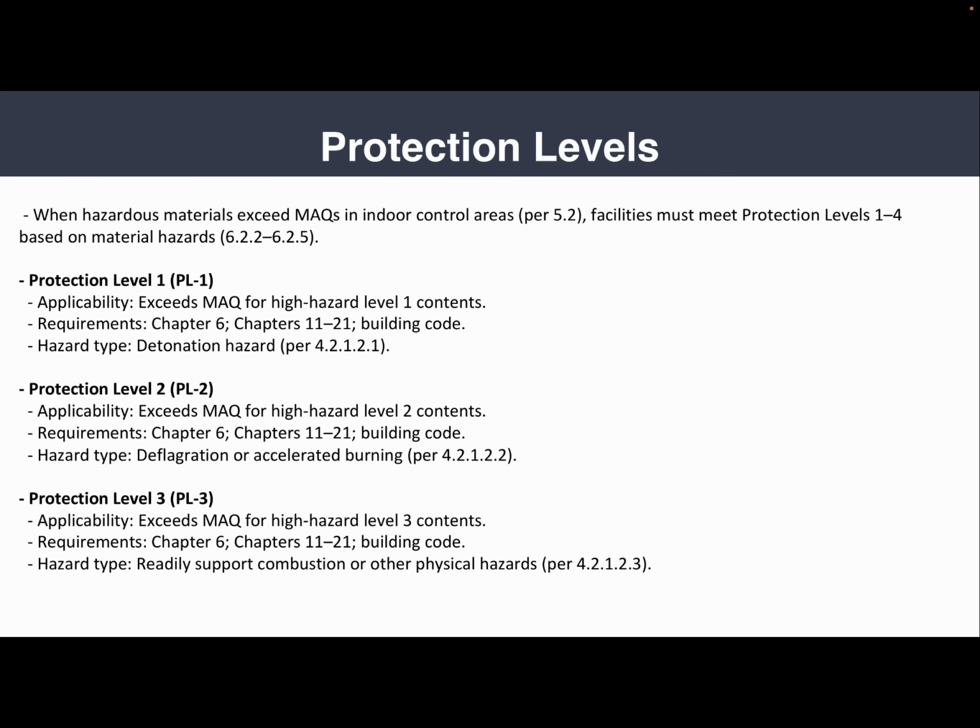So to wrap up our lecture, let's summarize the key points. NFPA 400 brings together multiple older codes into one unified document that manages the safe storage, handling, and use of hazardous materials. The DOT classification system focuses on transportation, while NFPA 400 focuses on building safety and design. The concepts of MEQ, control areas, and protection levels are the foundation of fire and life safety when dealing with chemicals and reactive substances.